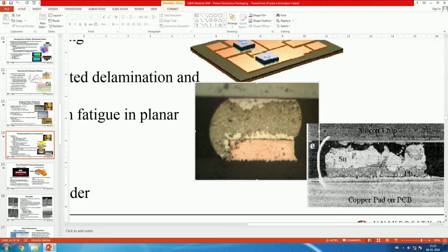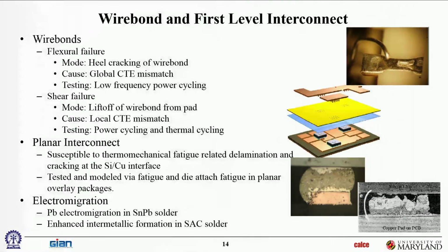But once that surface becomes more smooth and flat, it's much easier to zip a crack through, so the apparent fracture toughness drops. So that's the real reason why excessive intermetallic is bad. Not because of the thickness, but because you've lost the waviness on the interface. And that's a discussion you hear a lot of times. People say, oh, I had too much intermetallic. No, no, no, you didn't have too much intermetallic. You had too poor an interface of your intermetallic. The thing is, it goes hand in hand, so there's a correlation. If you had too much intermetallic, chances are you also had a poor interface.